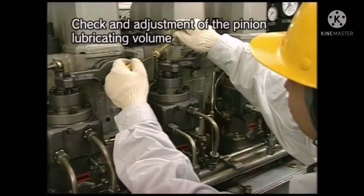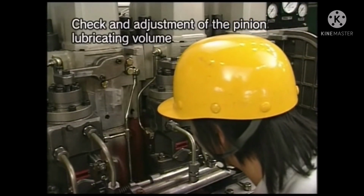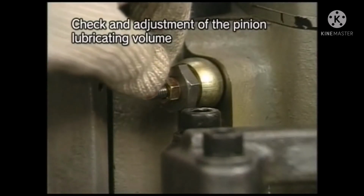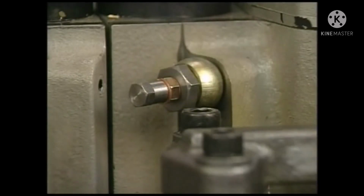Gradually loosen the adjusting screw and make an adjustment in such a way that the oil drips at the rate of 1 drop every 10 to 12 seconds. Securely tighten the lock nut, cap nut, and plug when the feeding quantity of the oil reaches the specified amount. Then the work will be completed.